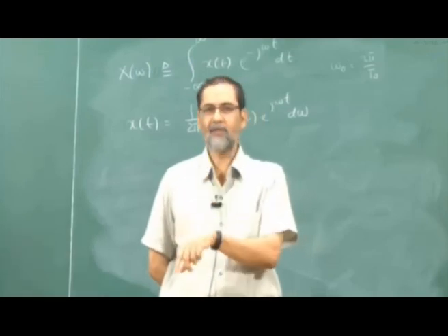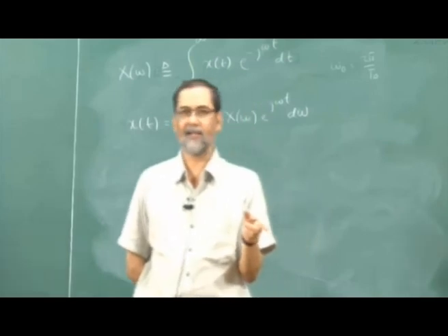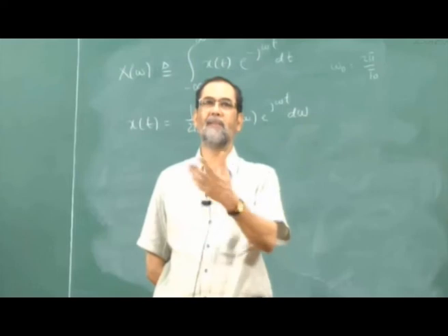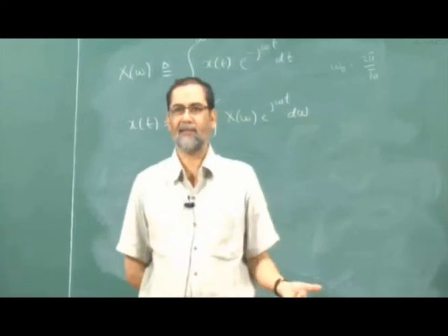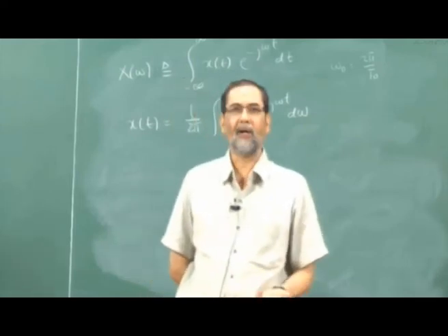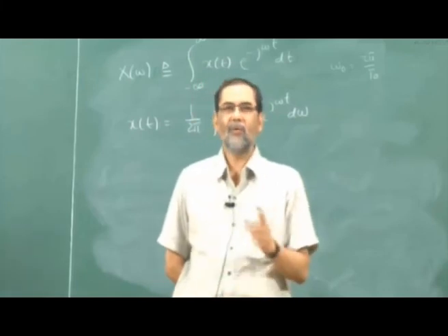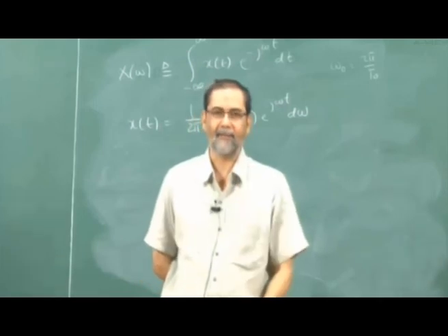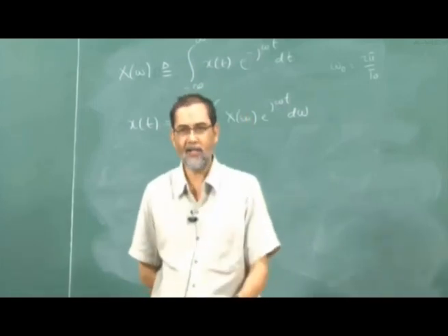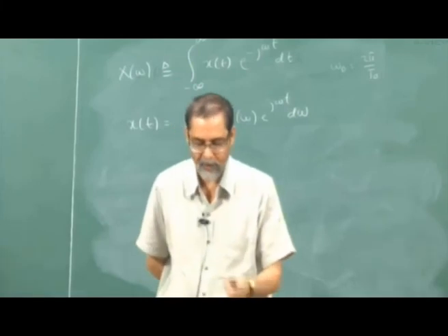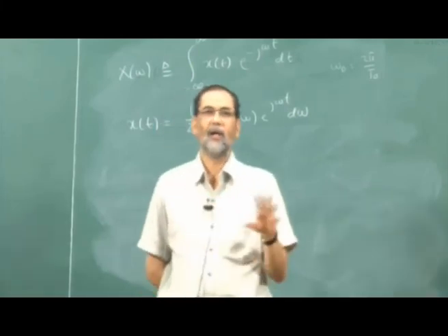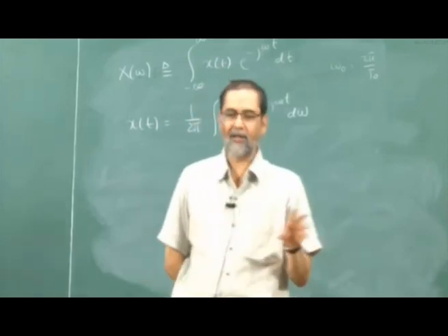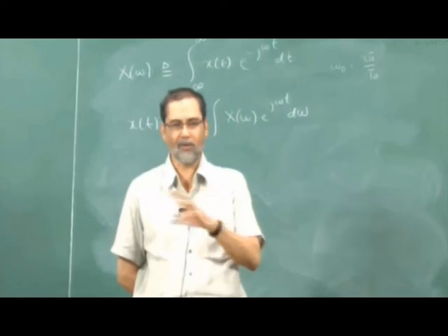An impulse response assumes an LTI system, right. Just because to any system you can give an impulse and some output comes does not mean anything, right. That is not a very useful thing at all. So impulse response makes sense only when the system is LTI, right. Only for LTI systems can I write convolution in terms of input and impulse response, right. And so please disabuse your mind from the thought that any system can have impulse response. That is not the truth, right.